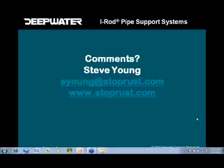As the pipe load gets to be too high, the pipe may bend before the I-rod changes because it's such a small point of contact. So in order to avoid that, as you saw in the pipe rack where there were multiple I-rods next to each other, it distributes the load across more contact points. So if you have such a heavy pipe that the pipe itself may be damaged, then what we do is install more than one I-rod at each pipe support, allowing that weight to be distributed among the different points of contact.